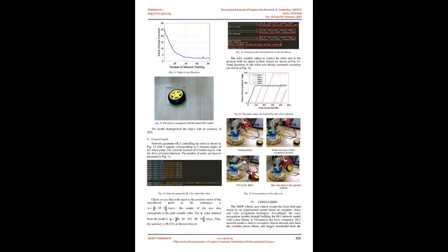The next action of the robot arm depends on the analysis results of the object recognition module, yellow wheel. To conduct the yellow wheel identification experiment, there are 3 objects including a yellow wheel, a green tray, and a red box. The image is divided into 7x7 cells. The identification algorithm uses 2 bounding boxes, nbox equals 2, predictions for each cell. The number of objects to be classified is 3, class equals 3. The number of images of each object in the library for training the DL2 model is 140. Each cell is a vector with 13 parameters.